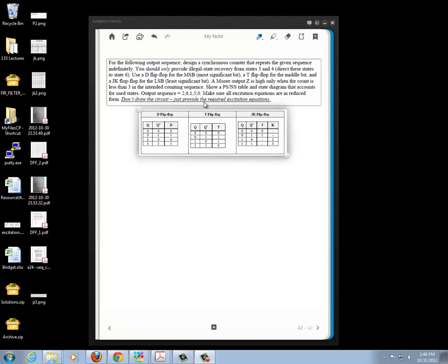Okay, so let's go ahead and see how this is going to look in a state diagram. I'm going to go ahead and make a legend first. We're going to have 3 state variables, I'll call them y1, y2, y3. And we're going to have one more output Z, and I mentioned that the Moore outputs get put in the state bubble. The reason they get put inside the bubble is because they're only dependent on the state and not on the inputs. Alright, so there's our legend.